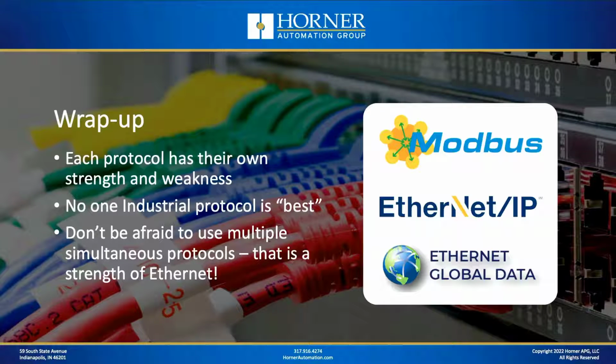And I will say one more thing. Don't be afraid to use multiple protocols simultaneously. If you have a host software program like a SCADA package, and it needs to be able to have access to your product or your machine, and Modbus TCP server is the best way to do that, use that protocol. But if you also want to provide access to or compatibility with Rockwell systems that are outside of your system, then also enable Ethernet IP as well. There's no reason why you have to stick to one particular protocol.